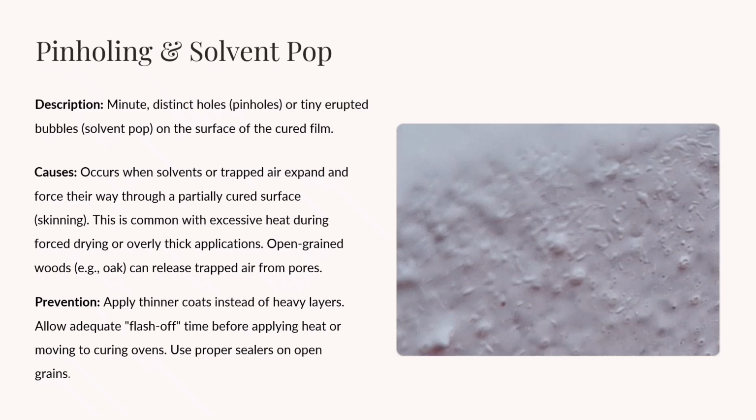To prevent this defect, apply thin coats instead of thick layers, allow enough flash-off time before drying, and use proper sealers for open-grained wood surfaces.